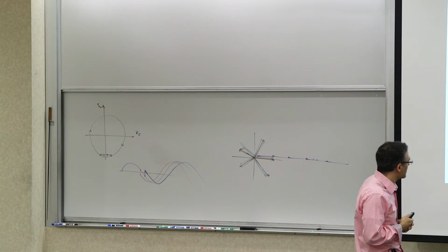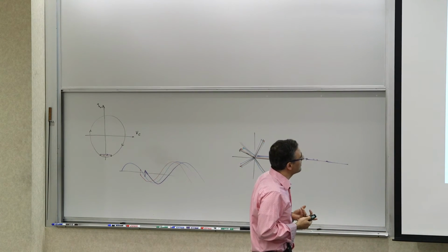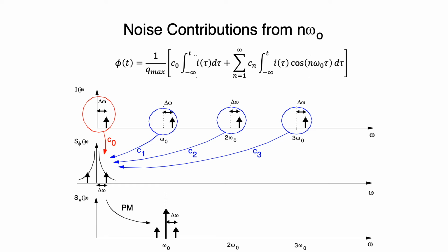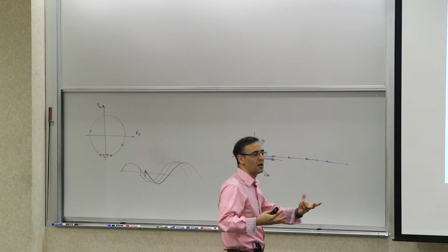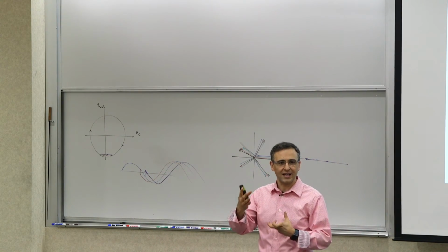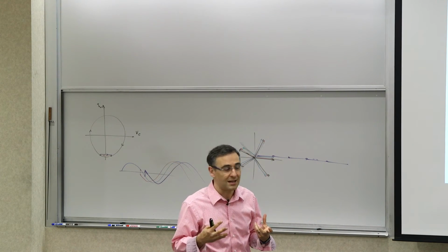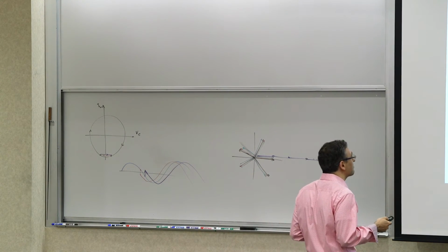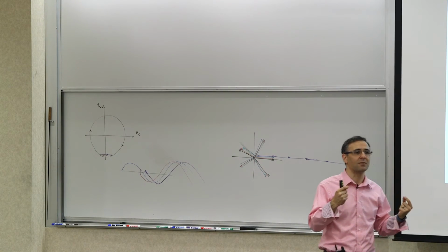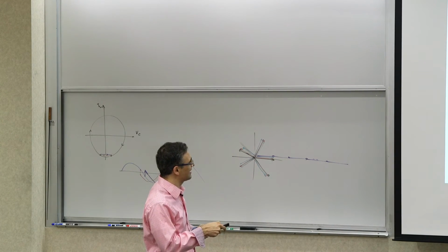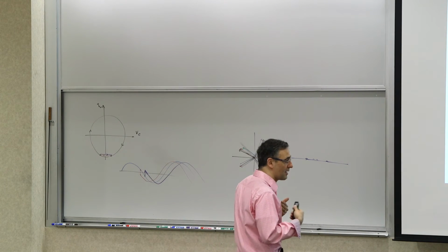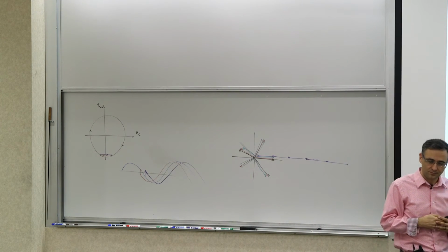So that's another discussion. So in general, if you have external perturbation to the circuit, it is the perturbations that are in the vicinity of the integer multiples of the frequency of oscillation that play the most significant role. So that basically tells you that if you don't want to have external signals, for example, there are scenarios where you have multiple VCOs or multiple signal sources running at different frequencies on the same chip or in the same system, and they couple to each other. So in your frequency planning, you may want to think about how you arrange them so that they do not coincide with something that's close enough to your system so that it modulates it the most. Because the closer it is to the frequency of oscillation, or an integer multiple of that, the more it would modulate that. Okay?